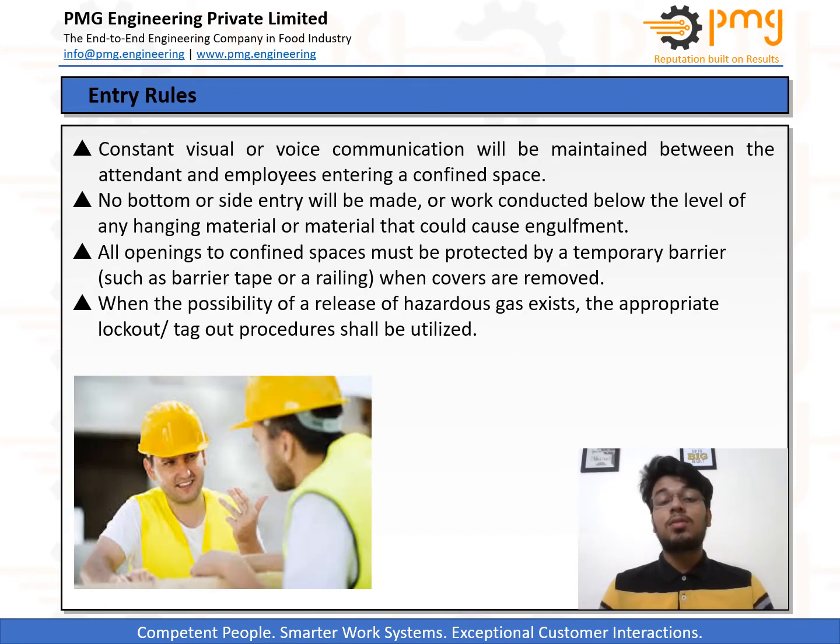Continuing with the entry rules one must follow while entering the space. The entrant should maintain constant voice communication with the attendant. In case maintaining voice communication is not possible for whatever reason, the entrant should maintain visual communication. The entrant should always enter the site from the top. Entrance from the side or the bottom may be possible, but it should always be refrained from. If there is a possibility of leakage, appropriate lockout or tagout procedures need to be utilized.